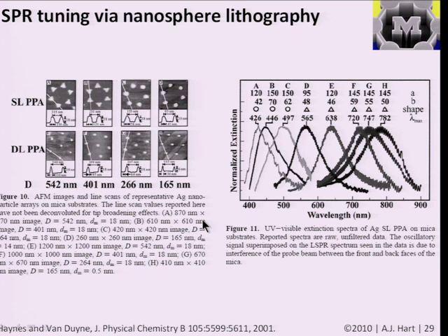But even with their mastery, the limitations of using an AFM, for example, to scan over these particles, because of the effect of the tip shape on the image, and the fact that if the tip has a certain angle, it's hard to measure the exact edge profile of the particle, means that these estimates of very small gaps between particles are only an approximation. So it really is hard to get an idea of the real true shape of the particle at a fine level, but certainly this ability to tune is there.